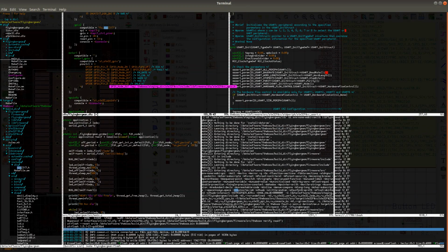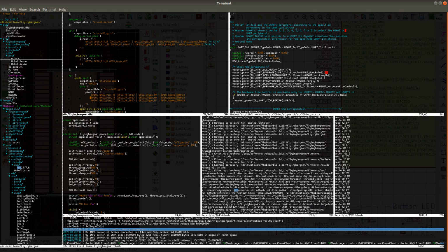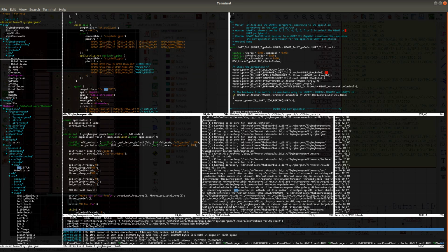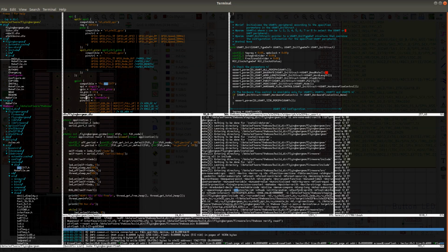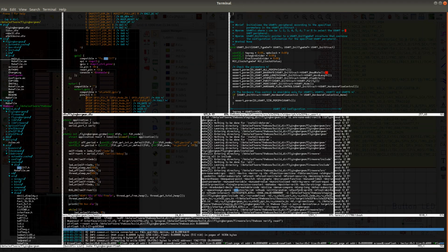Okay, so this will be GPIO mode AF, and we can define it similar to this definition. So we'll have AF, then the name of the timer, and we're going to be using push-pull, and we could